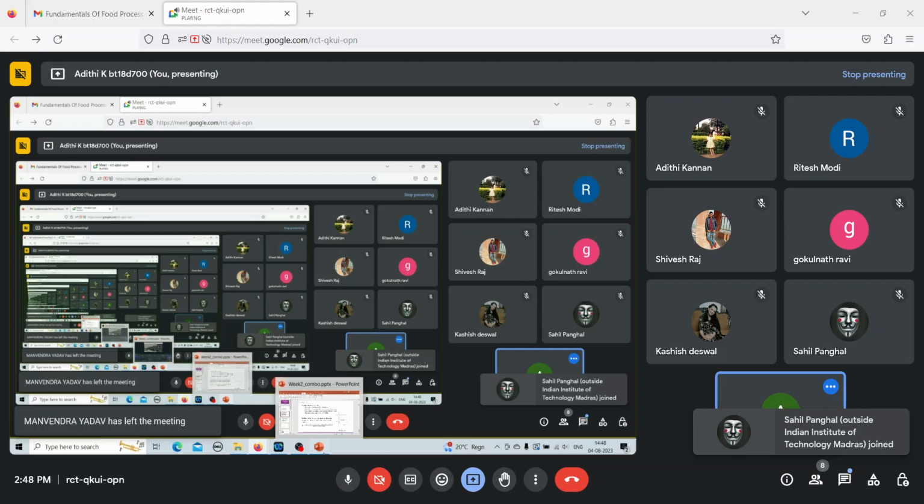Let's say this is your relaxation time. Somewhere here is your relaxation time, and this is your Deborah's number's denominator. That is the total time that you are taking to observe the material. Is this part clear? Do you remember what Deborah's number is? It is relaxation time by total time. That is Deborah's number.